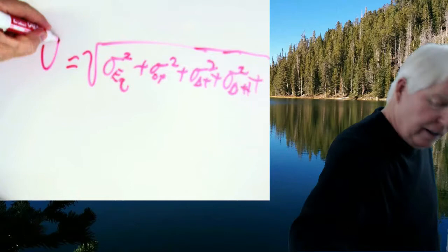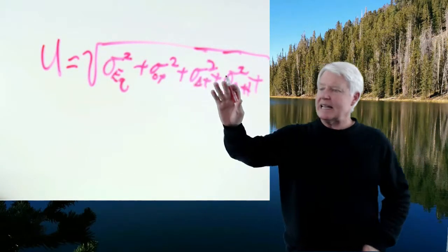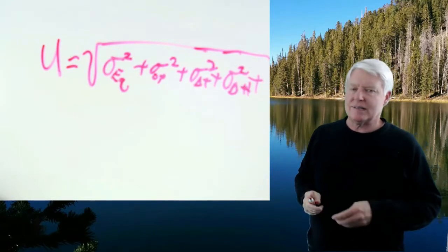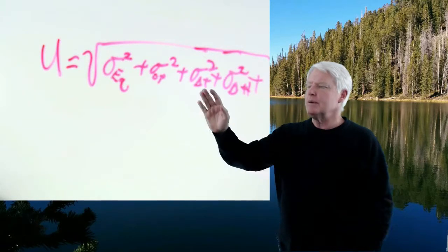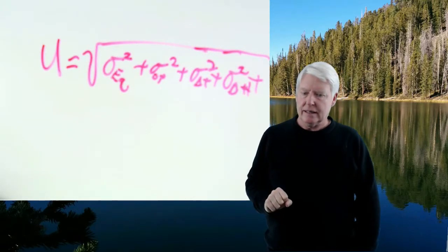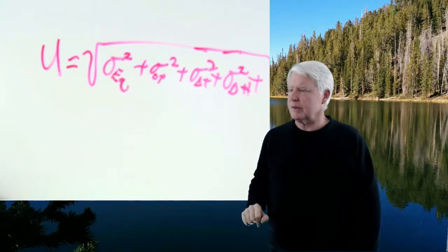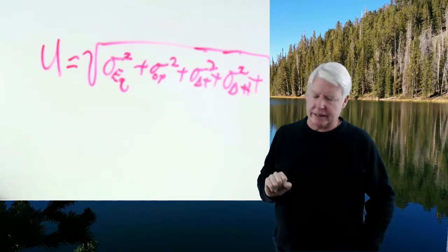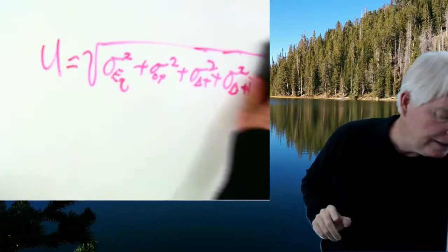This is called uncertainty. That sigma total in measurement is called uncertainty. I don't have enough room to write it, so I'll just call it uncertainty. But any standard deviation that's important and impacts measurement in a negative way is assumed to be part of uncertainty. And so it's pretty big. There's precision. Sigma of equipment, of course, is precision. And there's also sigma of the standard you could put in there. There's all kinds of sigmas you could put in there. But that's called uncertainty. So hopefully that helped you.